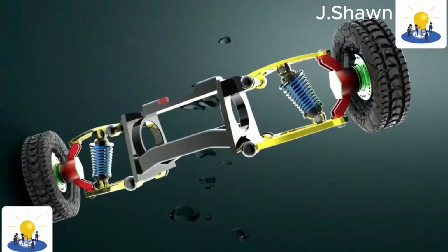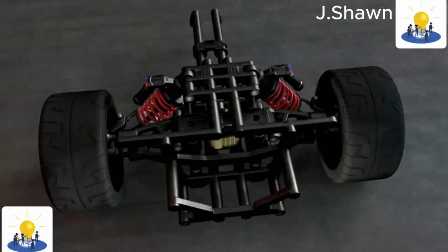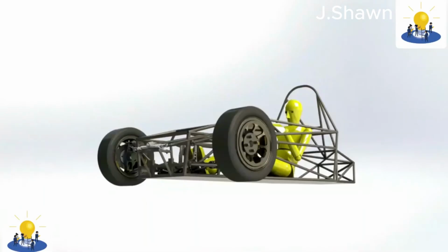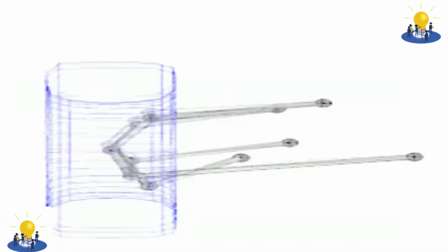Advantages. The double wishbone suspension provides the engineer more design choices than some other types do. It is fairly easy to work out the effect of moving each joint, so the kinematics of the suspension can be tuned easily and wheel motion can be optimized. It is also easy to work out the loads that different parts will be subjected to, which allows more optimized lightweight parts to be designed.